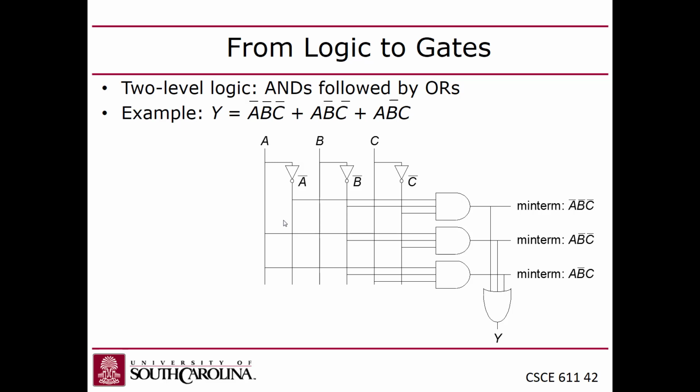So in this case, I've got A, B, and C come down vertically, and then going horizontally is where I form each minterm by connecting each wire corresponding to an input or its negated form using these T junctions. And then those run into these AND gates, and then there's another vertical plane here for the OR gate that combines together the minterms. Does that make sense?